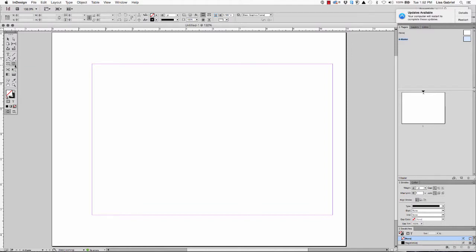So click on the rectangle tool and we're going to set some parameters at the top. So whenever we're clicked on a tool here, we get the control panel at the top and we're going to set some parameters. We're going to pull down where it says 1 point. We're going to pull down to 0.05. What this is determining is the thickness of the border around the rectangle that we're about to draw. And this is going to determine what type of border it's going to have. In this case, we're just going to have a solid black line border.